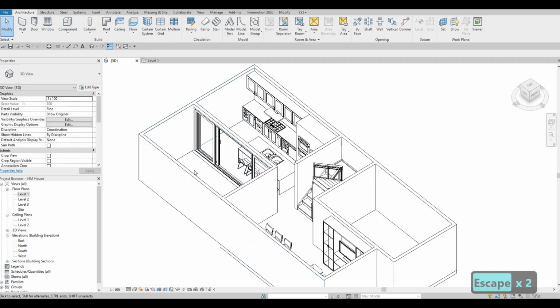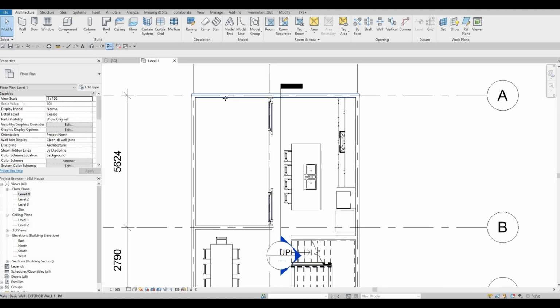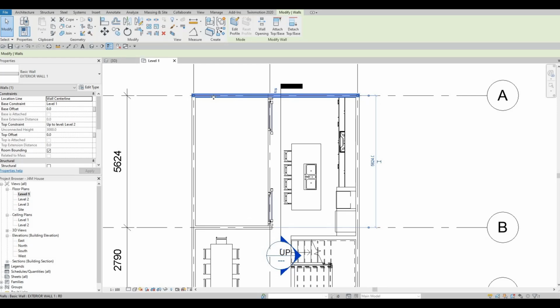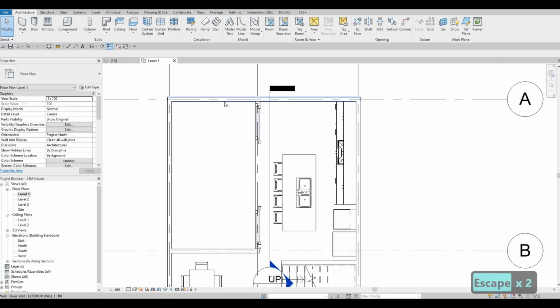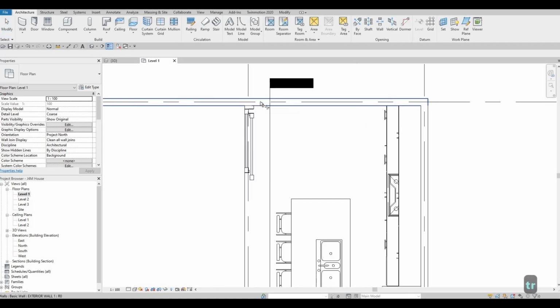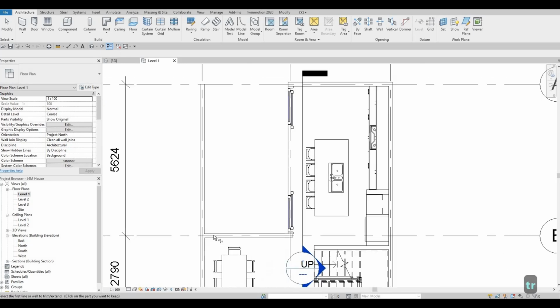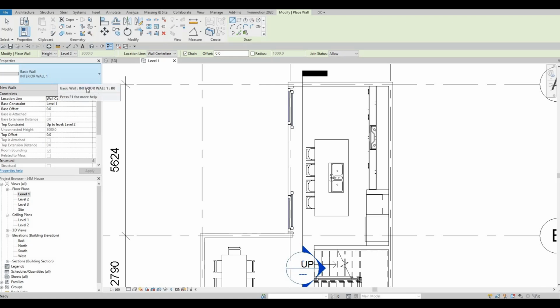At the same time, we're gonna put grass around there. So first I want to pull back this basic wall, exterior wall number 1, because I want the border wall to be smaller, and I want it to have a different material. So I'm going to type in TR, that's trim and extend, and then trim and extend right here. And then after that, press escape multiple times, and then click on wall again, and then we're going to create